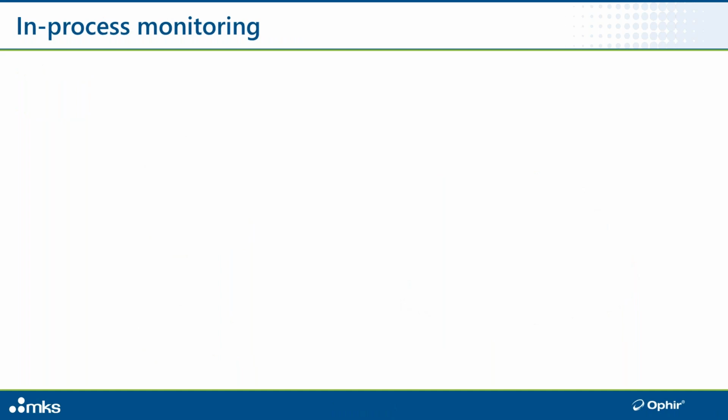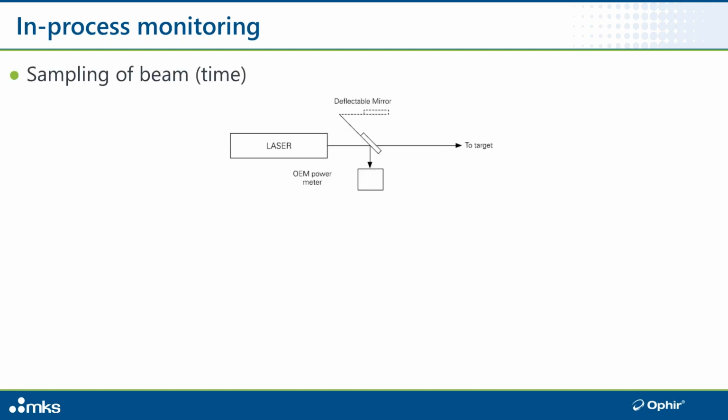Very often the sensor is used, and I think this is already touching on something of more central interest to our topic, to provide real-time feedback control to the laser built into an application, into a process. In some applications, this sort of self-calibration of the laser system is performed periodically, say once a day, once an hour, once an X, or maybe before each new workpiece or run of the process as relevant.